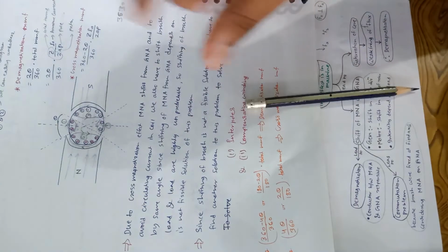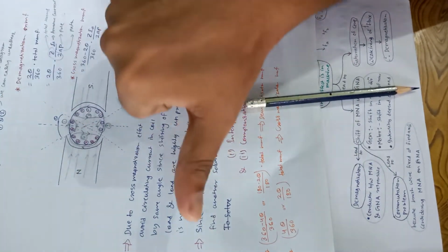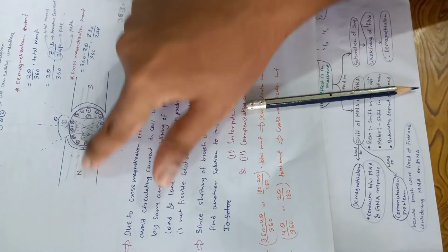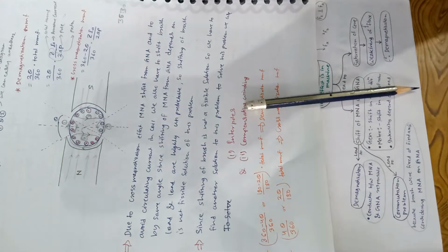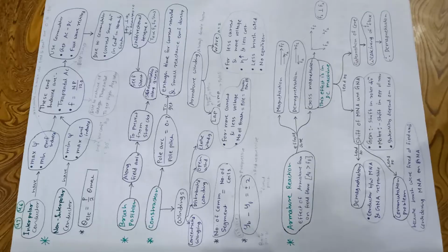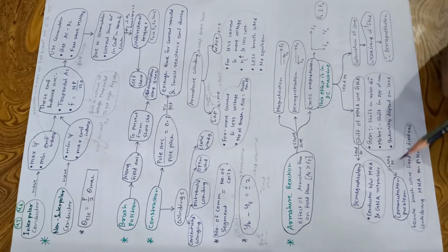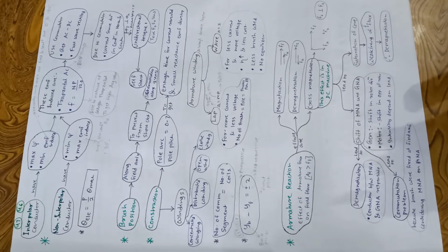See, due to this the flux will be like this. Flux is like this, which means it will oppose the field flux. Opposing the field flux means demagnetizing. Okay, this is what we have to see. So now we have to counterbalance this commutation problem, demagnetization and cross magnetization.